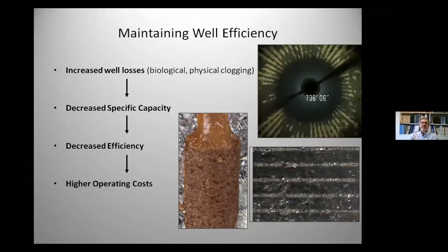Because things like scaling happen. You could have mineralization clogging those screen intake areas. You can have physical clogging. Fine sand can clog very fine slots on some screens, and this blinds it. This is going to cause further head loss in the well. This right here, this is bacterial buildup. This will also be a large contributor to head loss because it's going to clog your screens and also be proliferating in the gravel pack zone itself too.